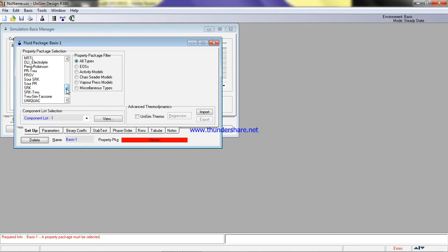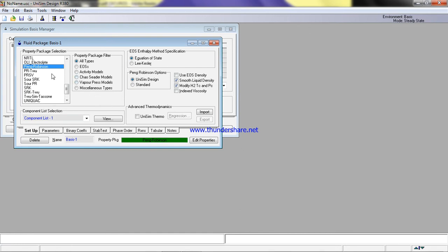You know, in the first degree, when you are doing thermodynamics, these are correlations that you use to estimate the process parameters manually. Like in my university, we had to estimate for Peng Robinson, for Redlich Kwong, and then compare the results. So we're going to use Peng Robinson. So you don't get to worry about which fluid package to use. If you use the wrong one, it will not show green here. Okay, so we close that.